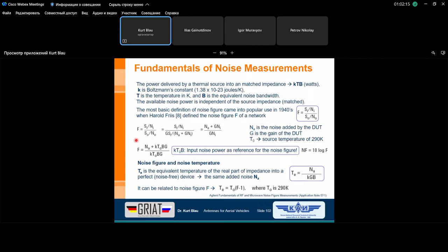Then we have another scaling, and in case of small noise figures the values are stretched, and we can also compare this. We can discuss a noise figure of, let's say, 1.2 and 1.4 dB. Okay, then we can see in the tenths value after the comma whether it's better or worse.